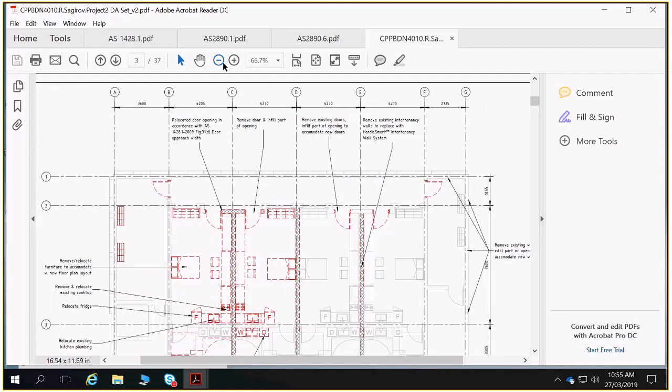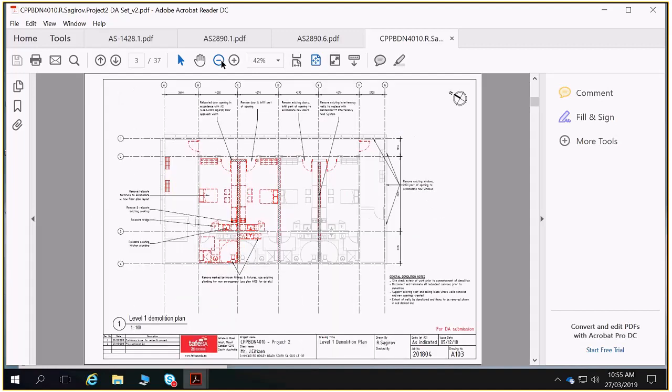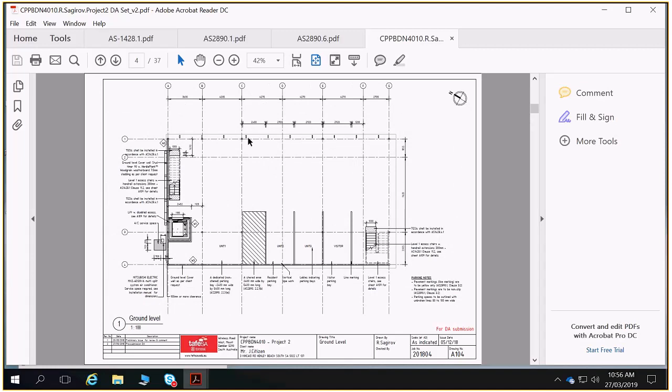7.6 meters spanning that with very little depth. Don't worry about those things too much. We have an existing structure and it's stood for years, but just remember that is a load bearing wall, and then we've got our load transfer support down the bottom through that front wall there as well through our columns here. So we can't really go messing with any of those columns. That's the main thing.